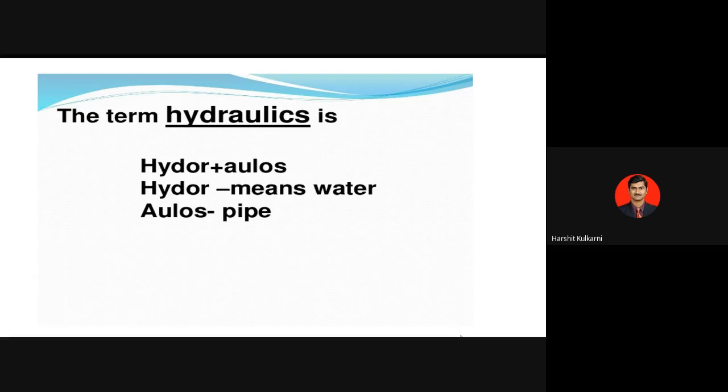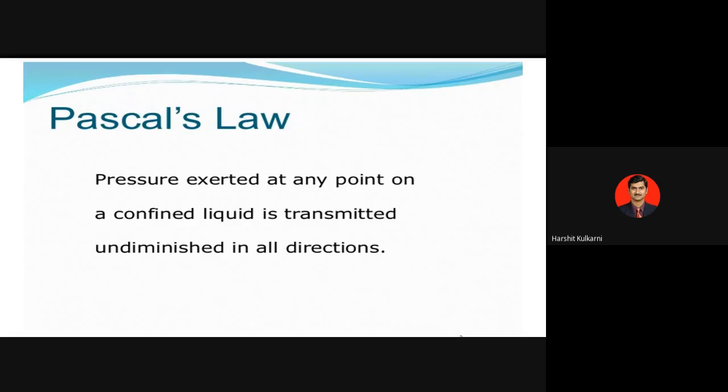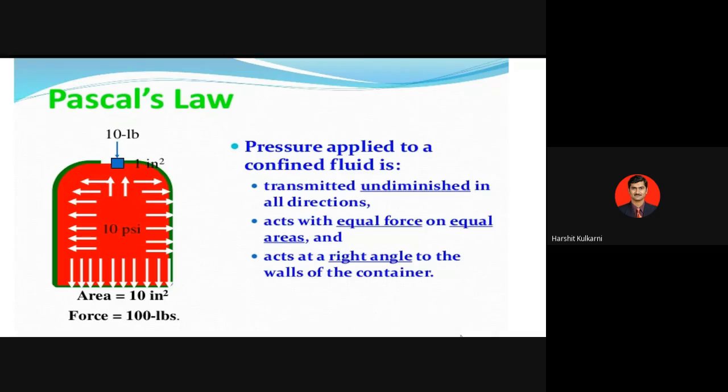What is hydraulics? It is a combination of two words, hydor and aulos. The base on which fluid power stands is Pascal's law. If you consider a closed container in which you fill the fluid, the pressure that is applied to this confined fluid is transmitted undiminished in all directions. It acts with equal force on equal areas, and at right angles to the walls of the container.